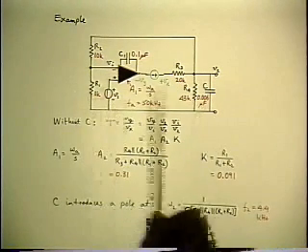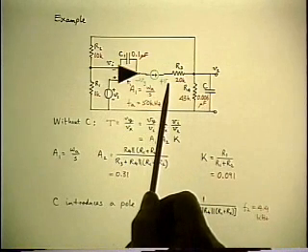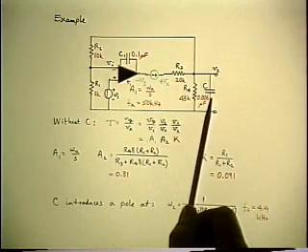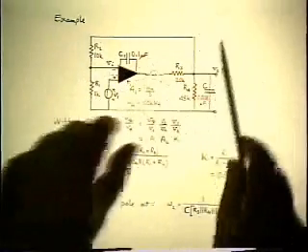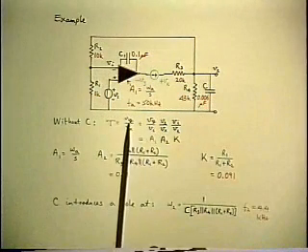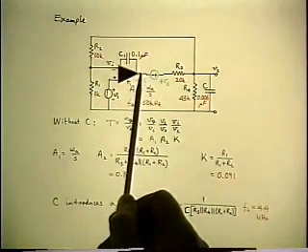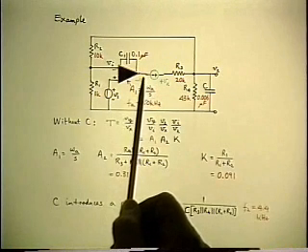Now you find the zero the same way. You restore the input, which is Vx. You apply the independent source in place of the capacitor. You imagine those inputs are twiddled until you null the output. The output for T is Vy. You propagate the null back to the second source in order to see what happens to its current.